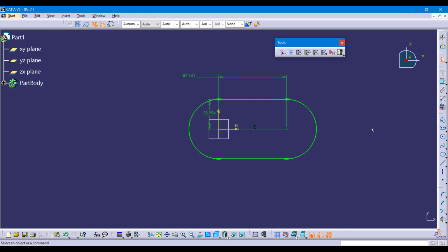The next thing that I want to do is define within the same sketch the shape of the next protrusion that's going to take place. Typically you have to do this as a separate sketch. However, if you're using the output features, you can combine them all inside of one single sketch. That is the added benefit of using the output commands, is that everything can be stored nicely inside of one singular sketch, and you can of course dimension off of these elements as you're constraining the sketch.